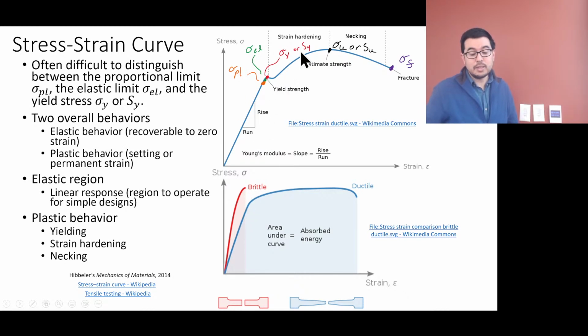Yeah, then it hardens. Yes, that is true. Okay, and so you can introduce what are called dislocations, and they kind of become like these hard knots. It's not wood, okay, but they become like these hard things in the structure that actually make the material stronger. Okay, and so this is one of the wonderful things about steel and some of these alloys, that you're able to increase the strength of the material by purposely plastically deforming it.